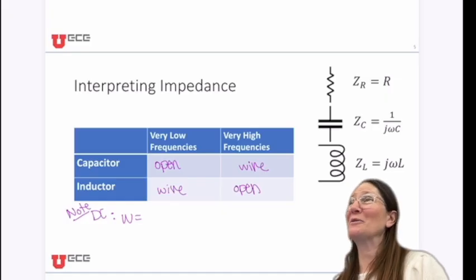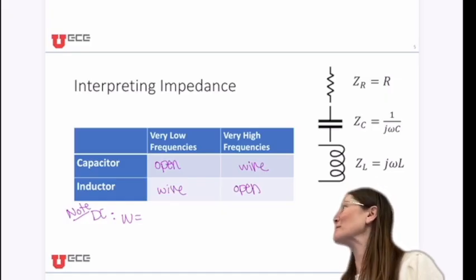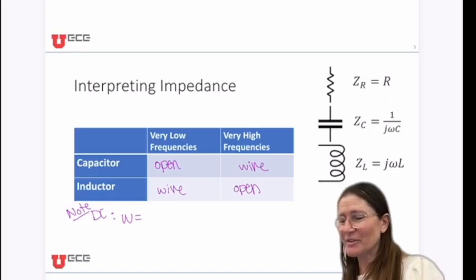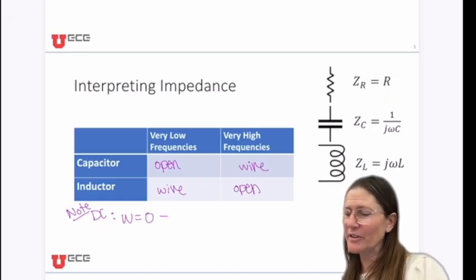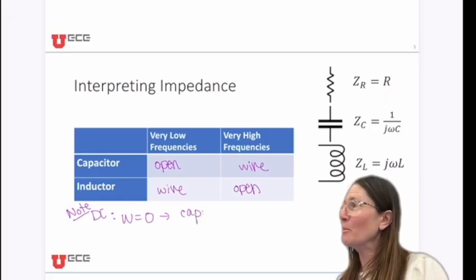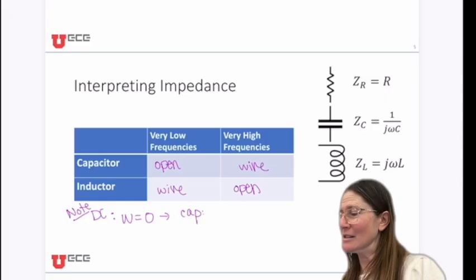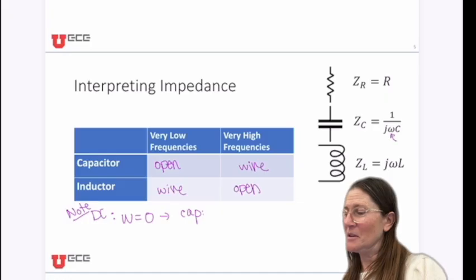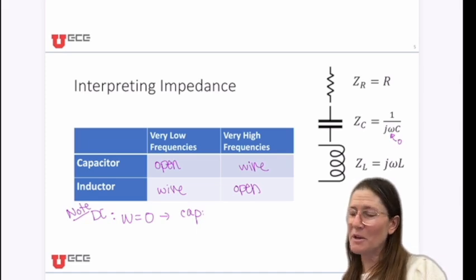Do you have any frequency? No. So what does it mean? You have 0 for omega, so what is this? Capacitor looks like a 1 over 0. Open.